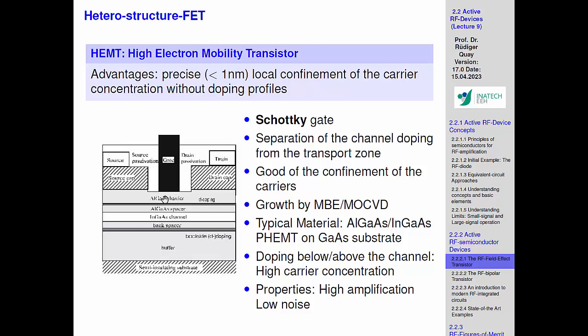And in a way, although the MOSFET is of a different type, it's a similar idea to the MOSFET, because the MOSFET also has a barrier, an oxide. And very near to that, you can modulate a sheet of carriers. The physics is actually a bit different, because in the MOSFET we have this inversion, which we don't have here.